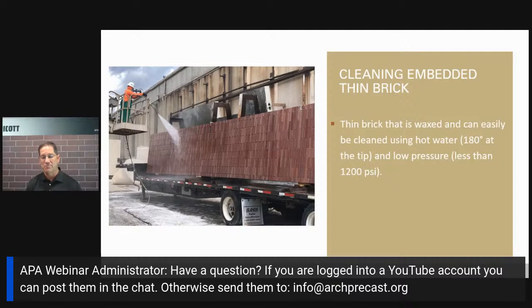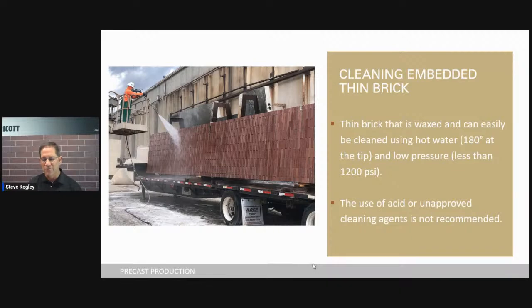And one of the coolest things as a best practice is make sure you do a test before you ever get into your panels. Make sure you do a test to make sure that the chemicals you're using are correct. Make sure that everything washes off properly and it looks nice when they're done. The use of muriatic acid or unapproved cleaning agents is not a good practice. Okay. And I know that in our construction industry for years and years, we've used muriatic acid or sulfuric acid that does a great job cleaning and creates all kinds of cool textures that you all have in the precast world when you're not using thin brick, and they look awesome.